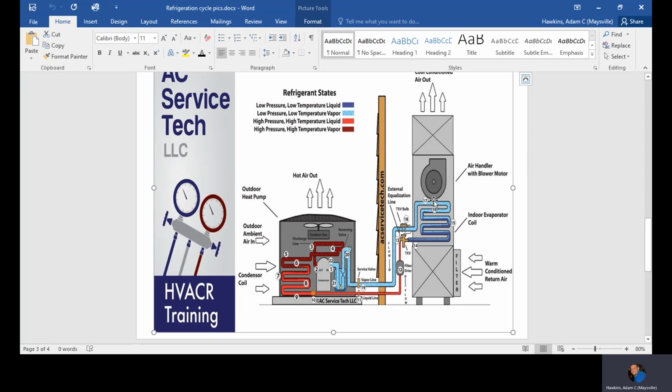So those fins slow down the air, and they're made of metal, so they're really conductive for heat. All of that works together for that heat to be trapped and go from the airstream into the refrigerant stream. So that's a transfer of heat. Heat from the air to the metal, from the metal to the refrigerant, and then from the refrigerant through the refrigeration circuit to eventually go outside. As a result, the refrigerant evaporates because it had heat from the house added on it.